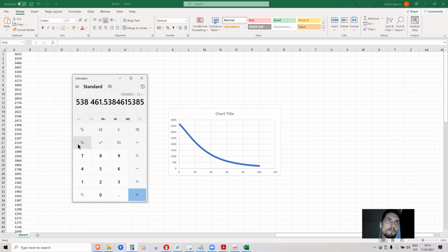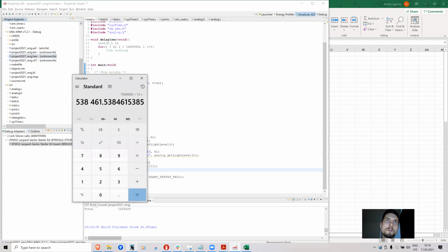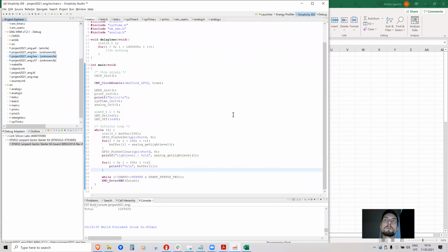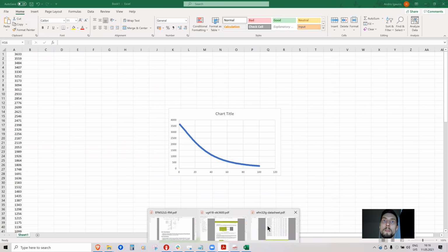Then we have some extra code for acquisition and buffer increments, but that's probably pretty fast, a little bit of addition. So we calculate the period of each sample. Each sample takes approximately 2 microseconds, and then we multiply it by 100. And we see that we need approximately 200 to 400 microseconds for this circuit to normalize.